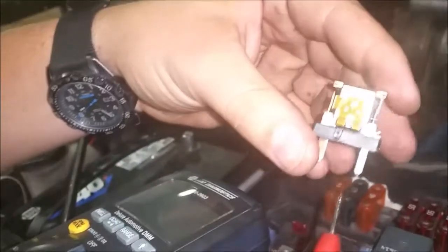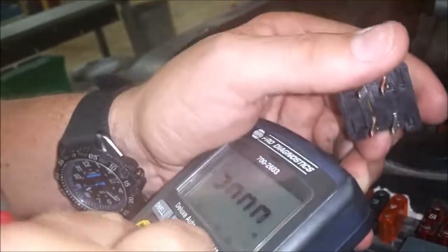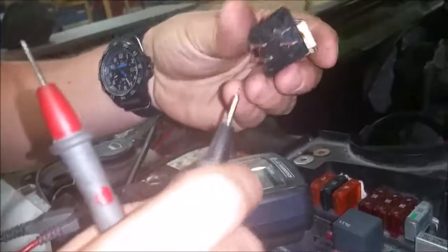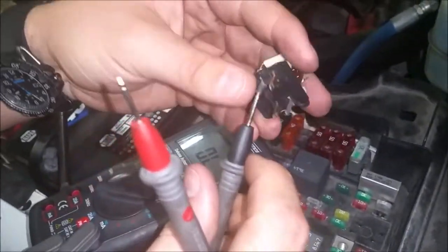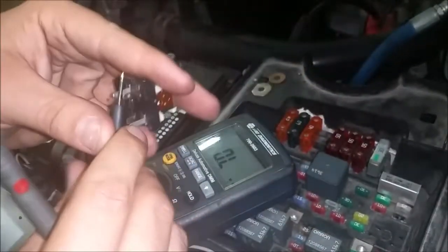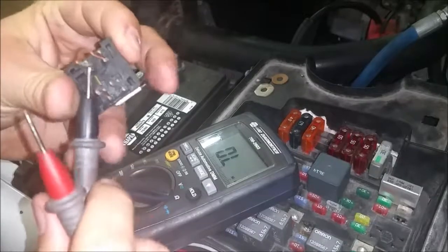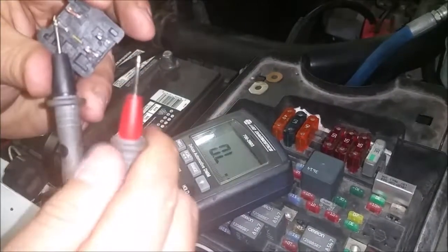You've got a coil. And with the multimeter, we can actually test this thing. So we're going to set it to ohms. We should get resistance in the, let's see, where's 30? There should be an open circuit between 30 and 87. We should get open because our switch is open. And it's open.